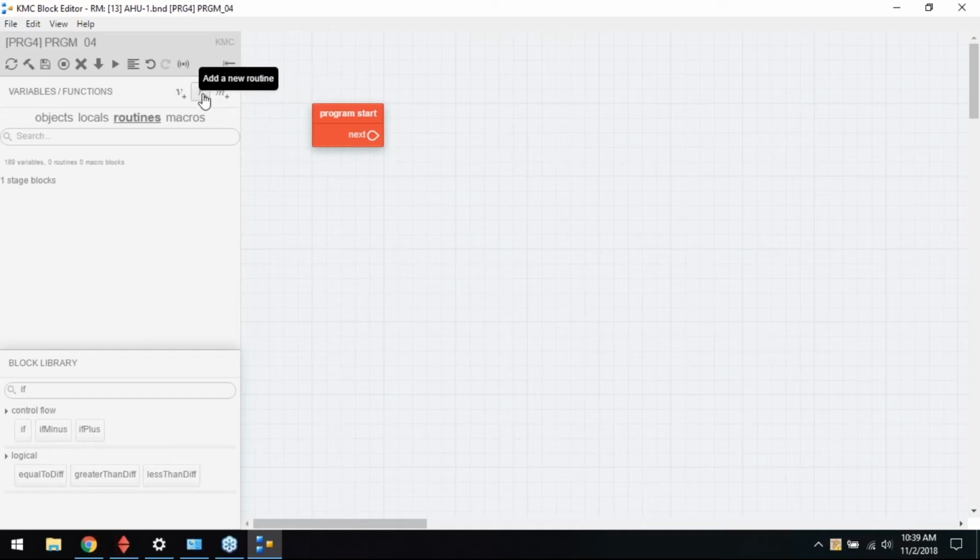So I'm going to hit R+ to add a new routine. And then we'll come over here and click on the little pencil, and we'll type in fan start. So now I've got a routine called fan start. We'll drag and drop him out here, and we'll connect him up because this is the program start. So you've always got to connect everything together so that it knows where the beginning of the program is and where the end of the program is.